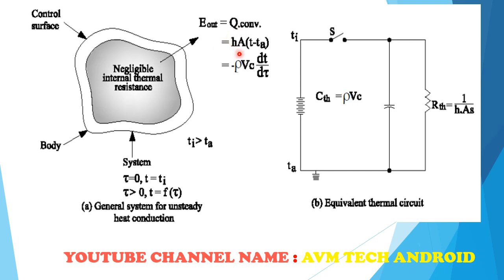This Q convection, that is hA delta T, is also equal to minus rho V c dT by d tau. So that is called m Cp delta T, that is mass into specific heat. Mass is replaced by density into volume, c is the specific heat, and dT by d tau is the variation of temperature with variation in time.